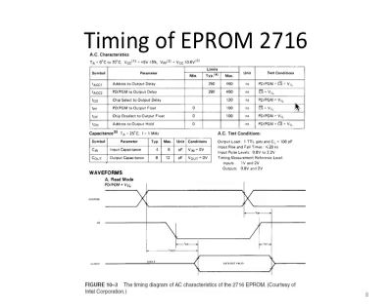The first signal showing up in the timing diagram, this is the address. And the second one is the chip select signal, and then the bottom one is the output. Now, the way to read this timing diagram is that for single line signals such as chip select, basically this line shows the logic high or low of this signal.